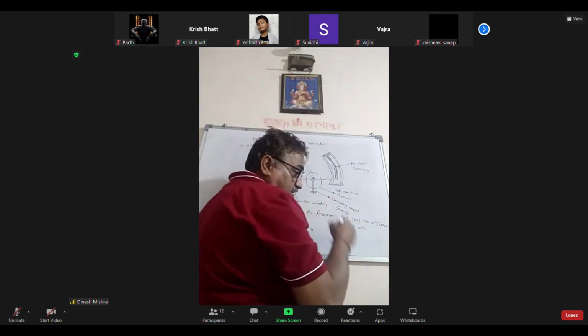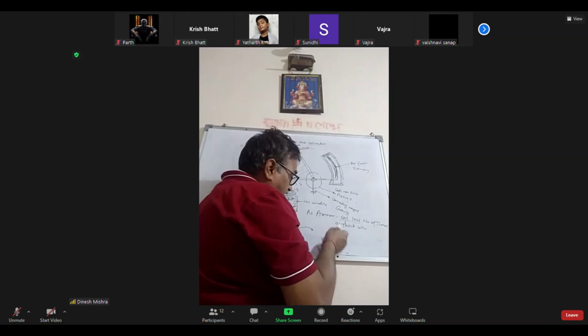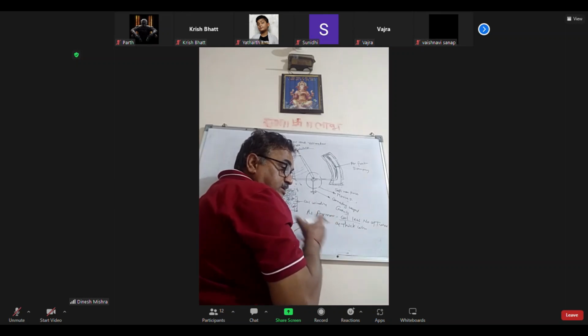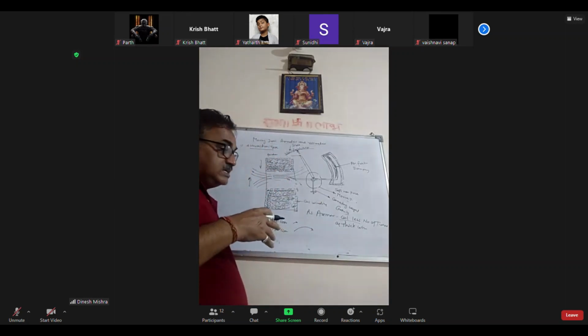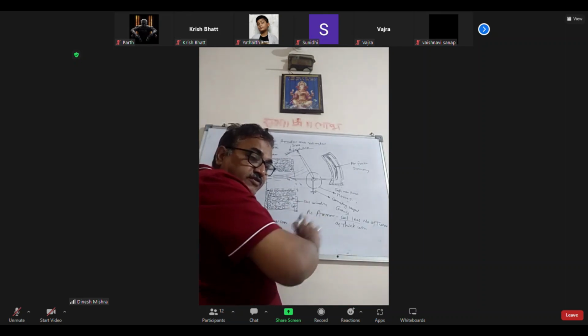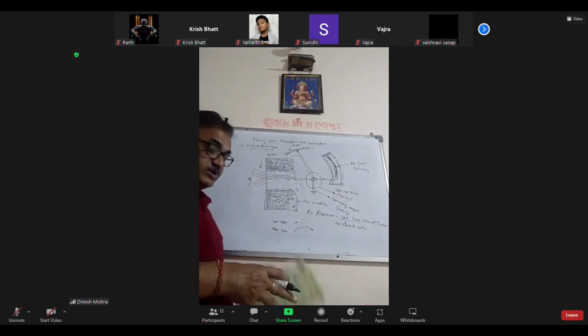अगर इसमें ज्यादा turns रहेंगे तो resistance will increase. Then the current will decrease, na. Resistance बढ़ेगा तो current कम होगा. इसलिए इसका resistance कम से कम रखते हैं, so that we can get an accurate reading of the meter.